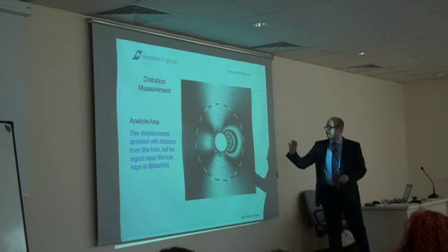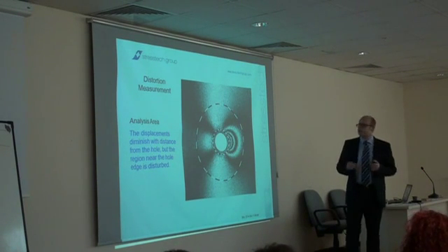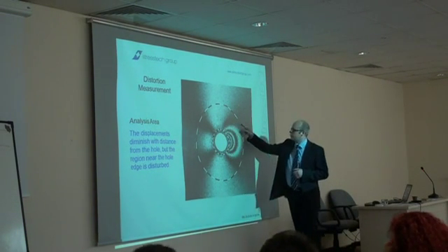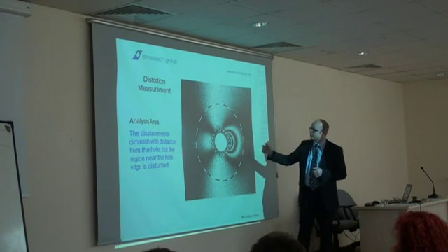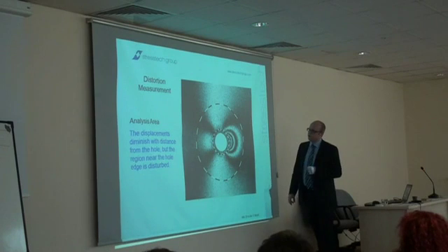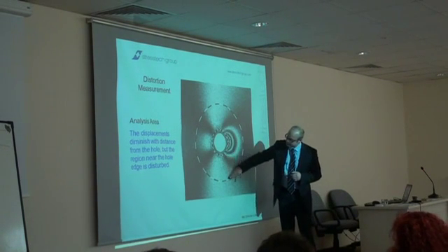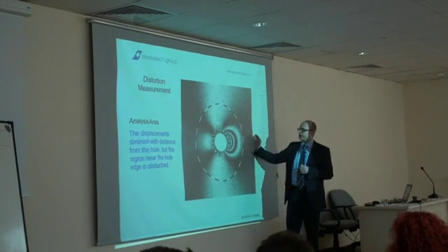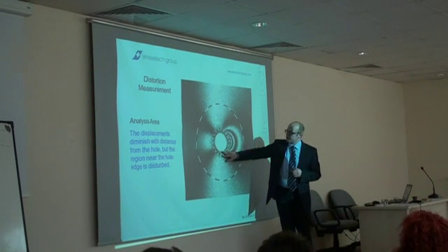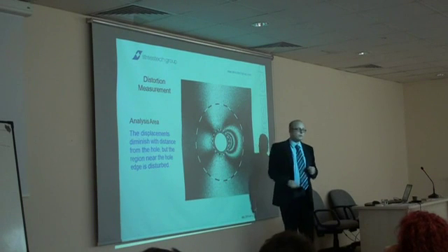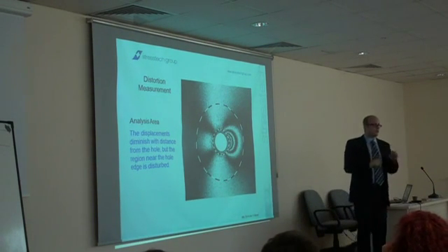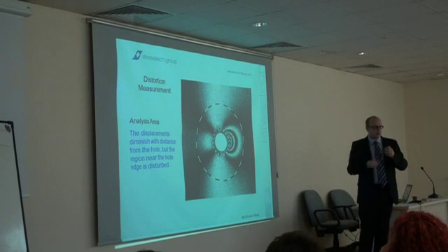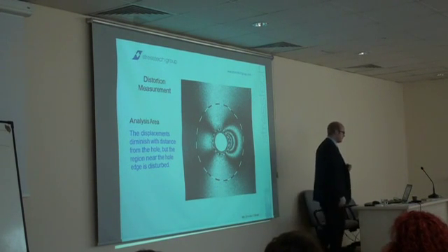And after measurement, we can set our analysis area. Typically, we use 2 times the size of the hole and 4 times the size of the hole. So the outer limit is 4 times and the inner limit is 2 times, which means we're analyzing this area here, because we cannot see so many changes after 4 times the hole diameter. And if we put the analysis area closer to the hole, there could be drilling chips that scratch the surface, and that has a big effect on the results.